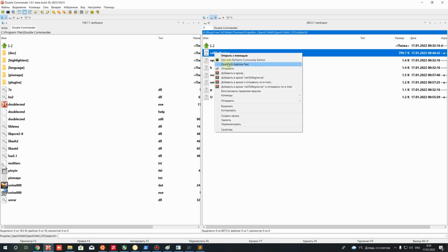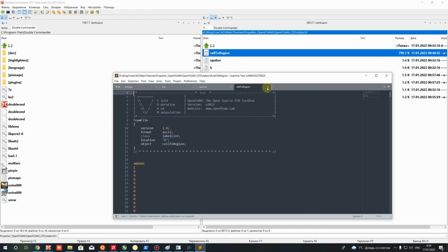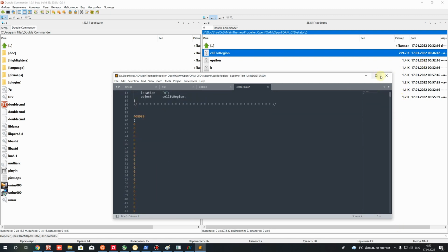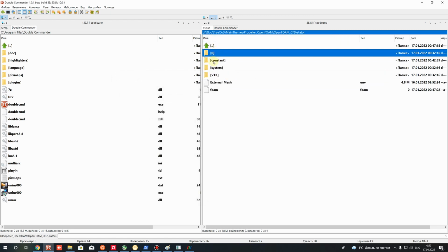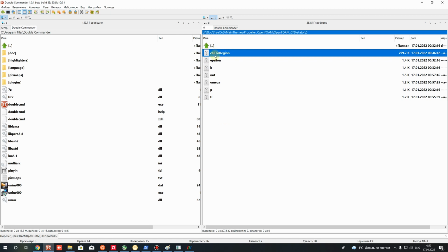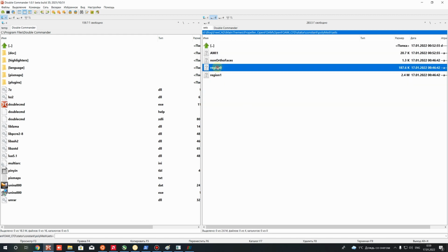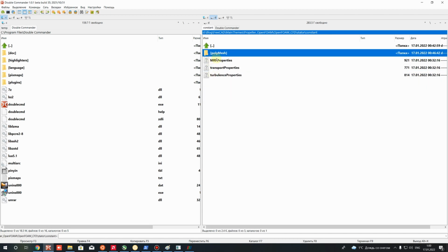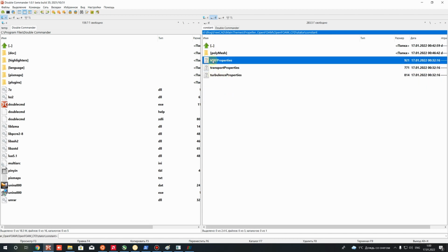This file was created automatically, just to show us where we have the rotor domain, and we have to recreate this file, and we have to create here the region of the rotor, because we will use the multiple reference frame approach for simulation of rotation of our propeller domain.